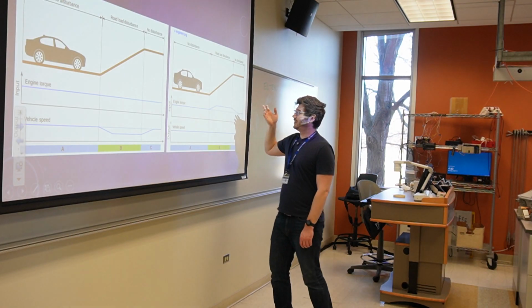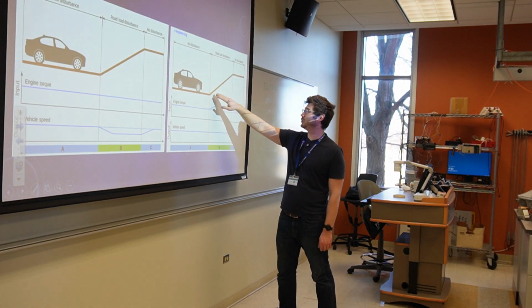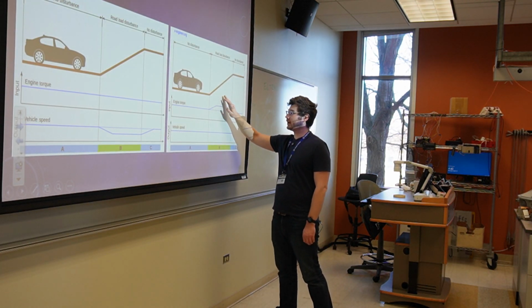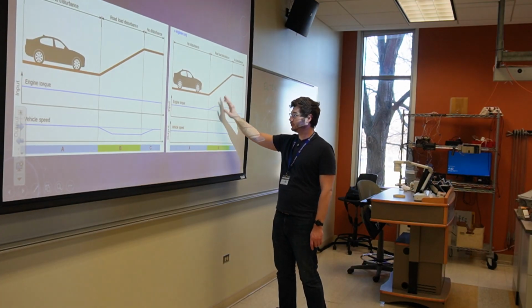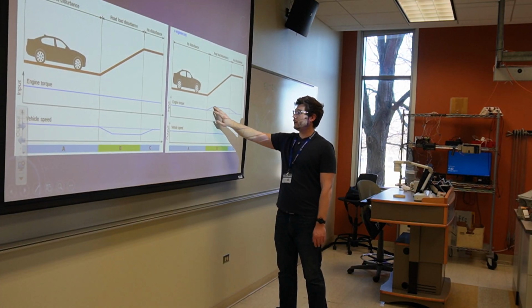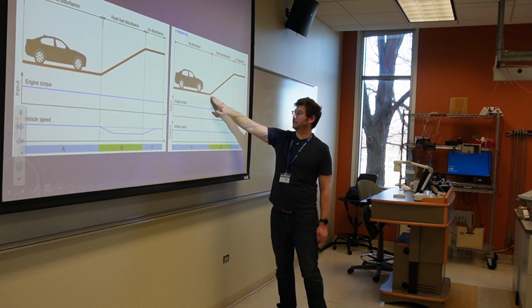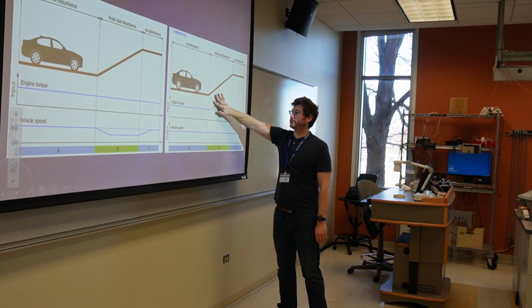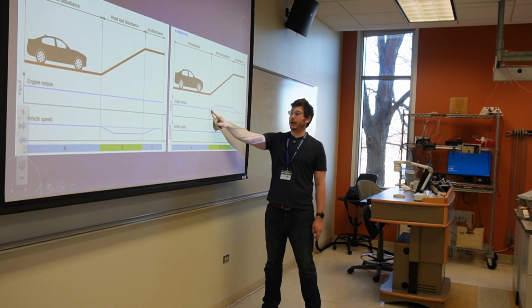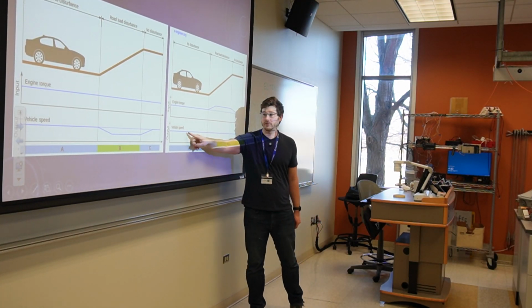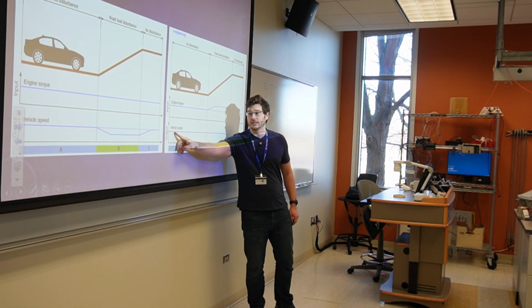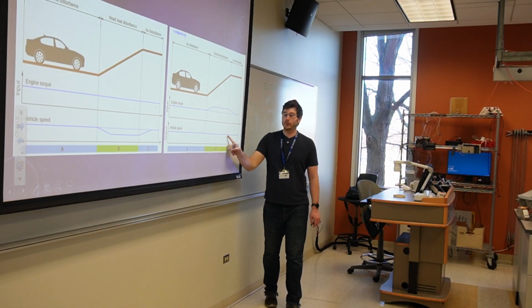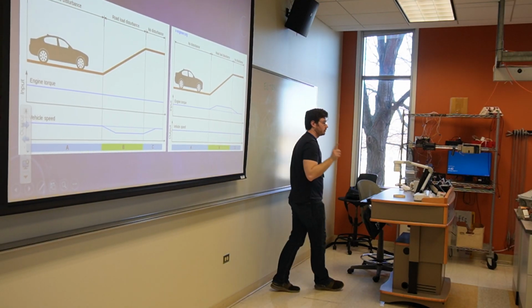Cruise control. It's talking to our cruise control computer, which, every instant in time it says, I know you told me to go this speed, but we're going a little bit slower, a little bit faster, and it'll command it appropriately. So as we hit that hill, we get that disturbance and additional force we need to apply to the vehicle. Our engine can respond appropriately, which means that our set point, which in this case is the vehicle speed, remains very close, low error, right, to what it should be.